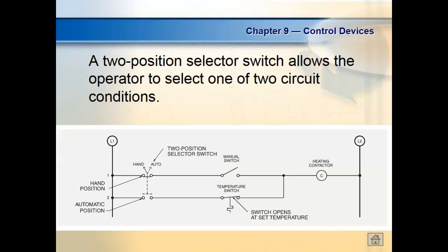But what makes it auto and what makes it manual? No, I'm talking about what physically makes it auto and what physically makes it manual. It's who wires the dang thing up and who puts that legend plate, right? It should say two position select. Ours is a three position selector switch, right?